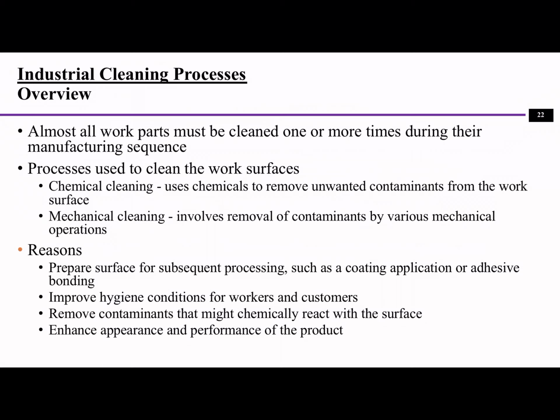And the reason we need to clean or process the surface is that either we want to prepare the surface for subsequent processes, for example coatings or adhesive bonding, or we want to increase the hygiene conditions for workers or customers, or remove contaminants that might chemically react with the surface, or enhance the appearance or performance of the product.